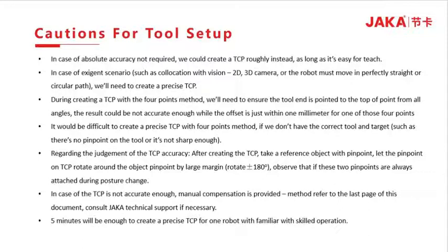Fifth, regarding the judgment of the TCP accuracy, after creating the TCP, take a reference object with a pinpoint. Let the pinpoint on the TCP rotate around the object pinpoint by a large margin, rotating plus or minus 180 degrees. Observe whether these 2 pinpoints always stay attached during a posture change.